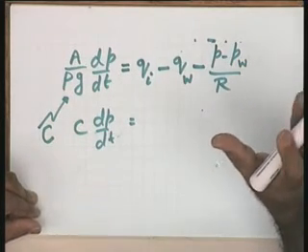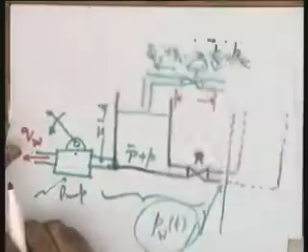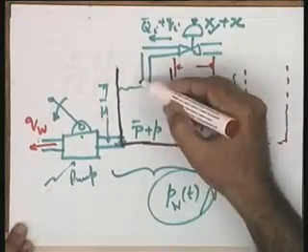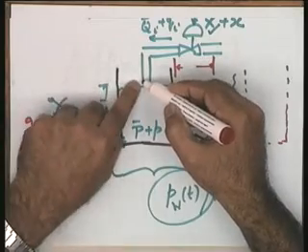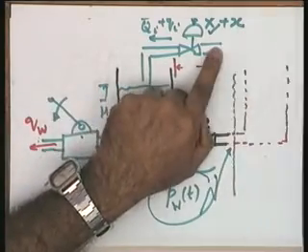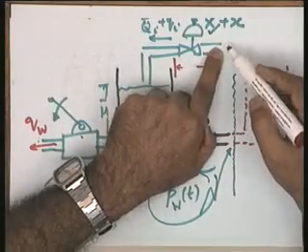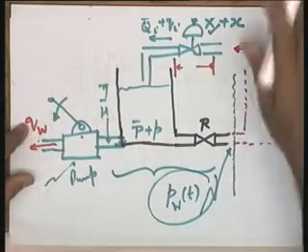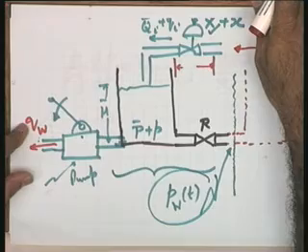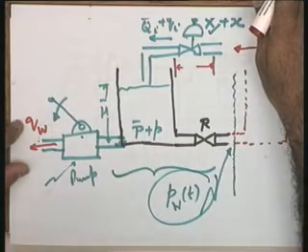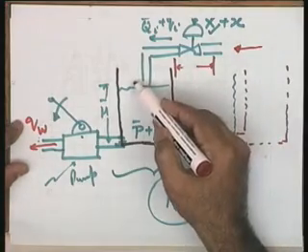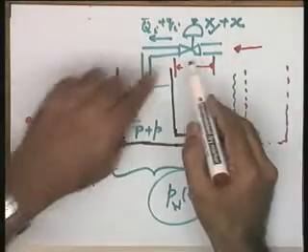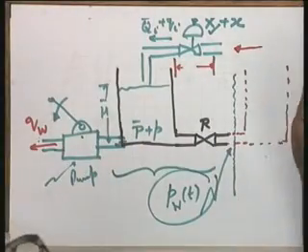The assumptions involved may be noted: in this particular case, how the pressure differential is getting established. Please see, what is the pressure differential across this? On this side it is the atmospheric pressure, on this side it is the overhead tank or the pump or any source which is supplying liquid. If I assume that input pressure, which may be the overhead tank or the pump, and the atmospheric pressure on this side remain constant, so under the perturbed situation the pressure differential across the control valve will not change.